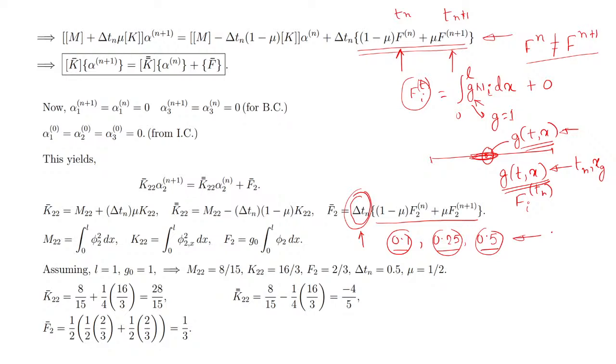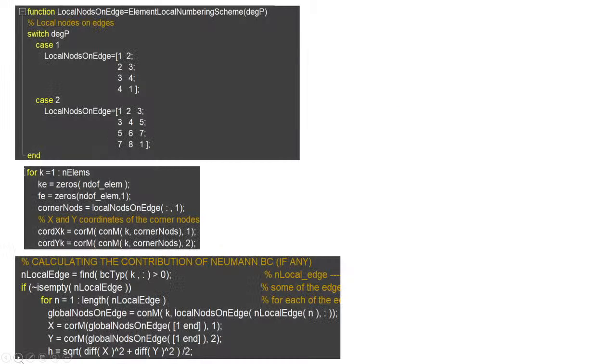Okay, in order to convince you that the solution does change with time step, we have actually taken this problem. As you have seen, as you take smaller and smaller time steps, your solution actually converges. All right, so that time convergence study, in addition to the mesh convergence study, is required for unsteady problems. So that was the purpose of the problem. Alright, so I think I have addressed your issue.